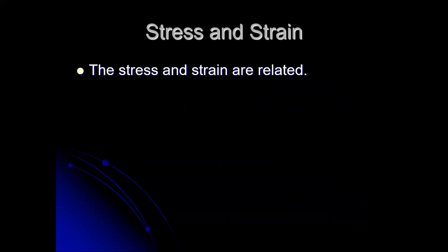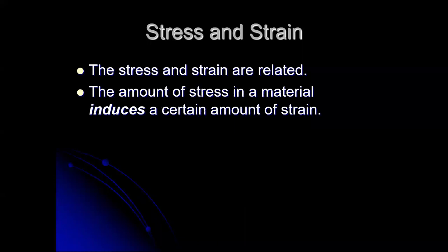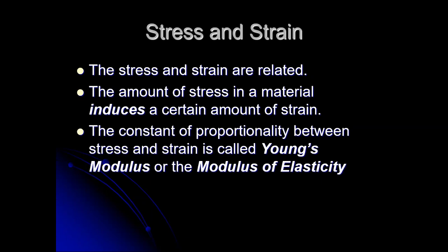Now, stress and strain are related to each other. Stress causes strain. We can predict from experiments that people have done, when you apply stresses, you'll get a certain response from the material in terms of the strain. Stresses induce strain. Stresses cause strain. Never goes the other way around. Something doesn't change shape first and then put a force on it. You put the force on, the material responds. You release the force, the material responds again. So stresses cause strain. There is a constant between the two that connects the stress and the strain, just like resistance connects voltage and current.